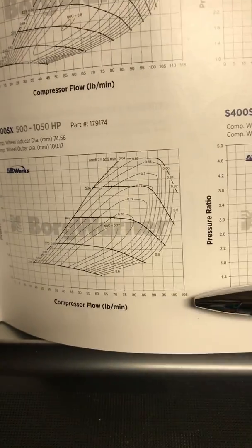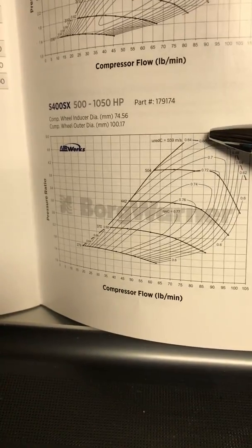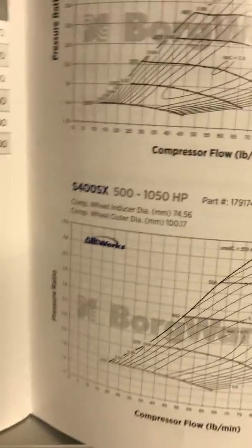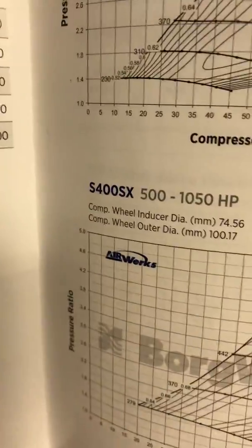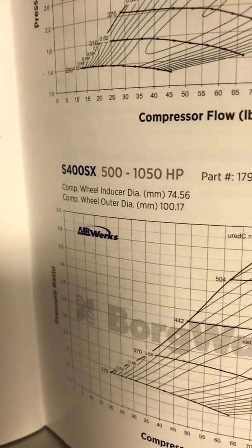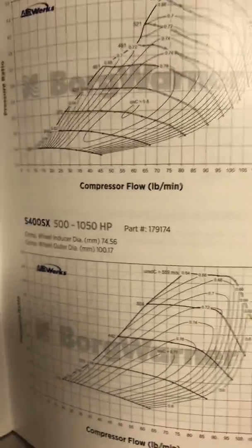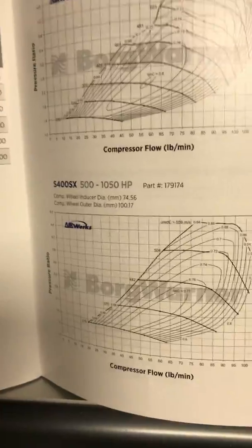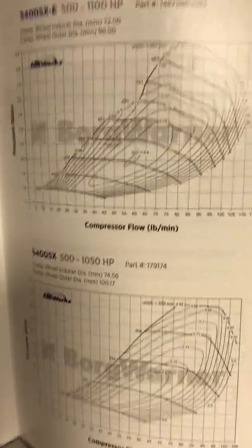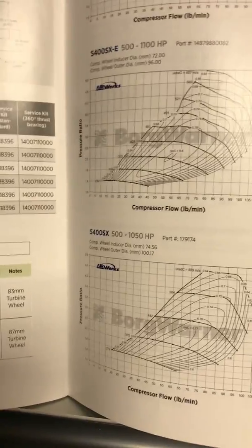86 pounds. First of all, 6-to-1 pressure ratio is off the chart. You're up here. Actually, you're up here a good bit further. You're overspeeding the crap out of the turbo. So anyway, we talked about this last time. We talked about how a 475 would barely get it done.